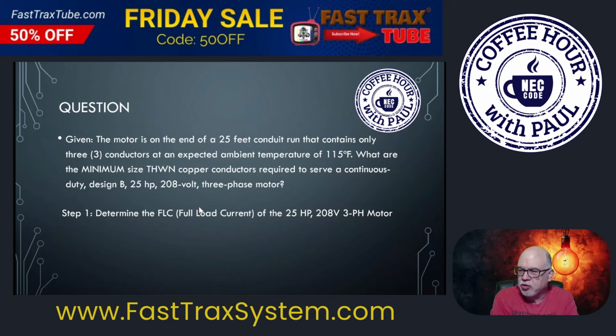So we don't have more than 3 current carrying conductors, but there is an ambient temperature of 115 degrees Fahrenheit, which deviates from the 86 degree Fahrenheit or 30 degrees Celsius ampacities that are given in Table 310.16 of the NEC. So we know we've got to do something there, right? This goes on to say, what are the minimum size THWN copper conductors required to serve a continuous duty, design B, 25 horsepower, 208 volt three-phase motor? Okay, so we have all the variables we need in order to size these conductors.